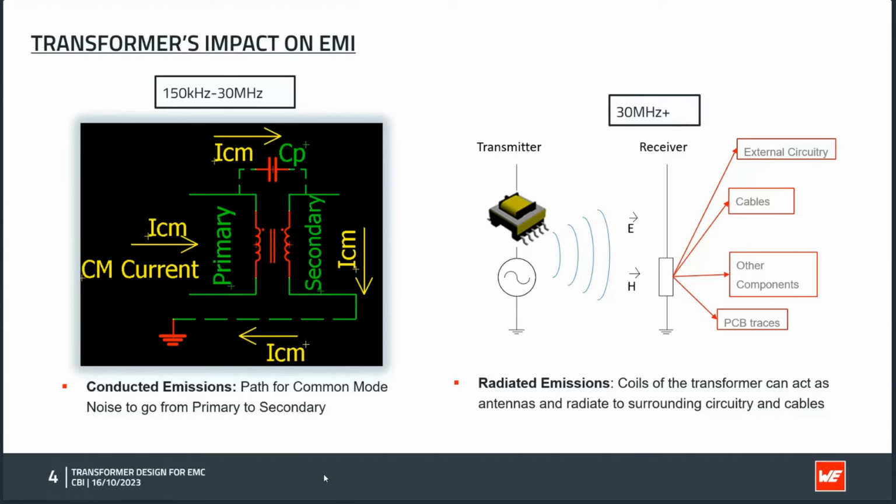And now if you think about the wire that is inside the transformer, a very typical length of wire can be in the range between 50 centimeter and maybe 2 meter. And anyone who has a radio station at home to receive radio signals, to listen to music, you know that maybe a 70 centimeter antenna is perfect to receive such signals. So we are here really in a range of wire length that can work as an antenna.